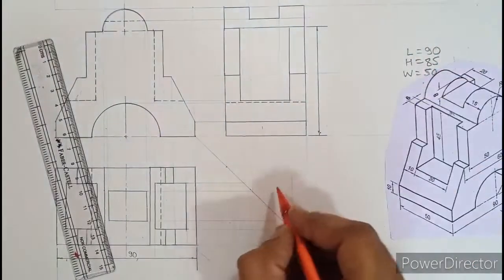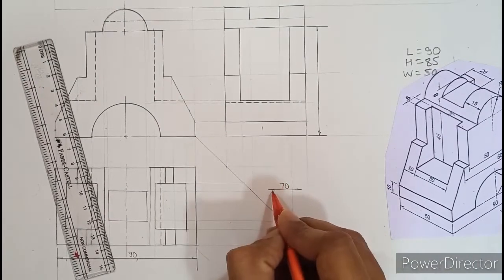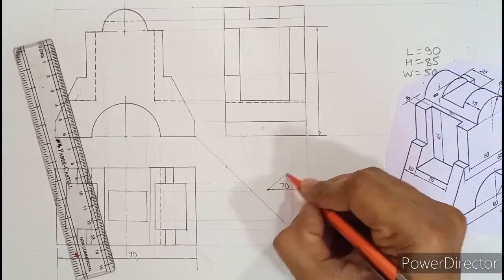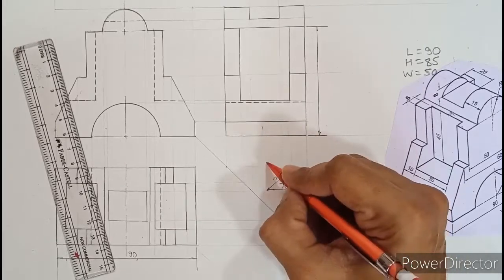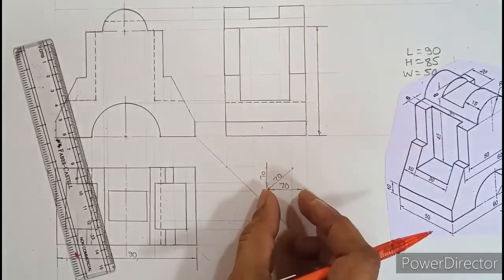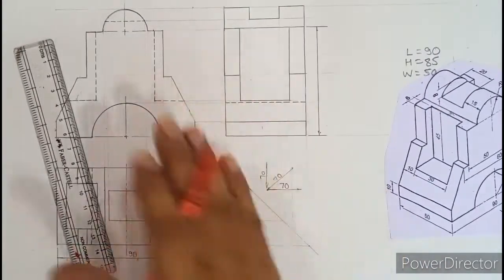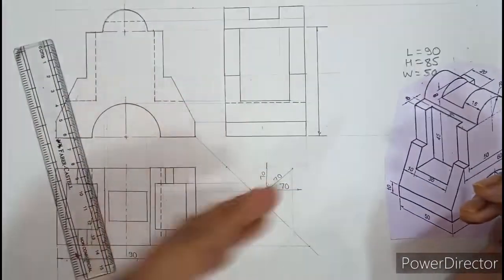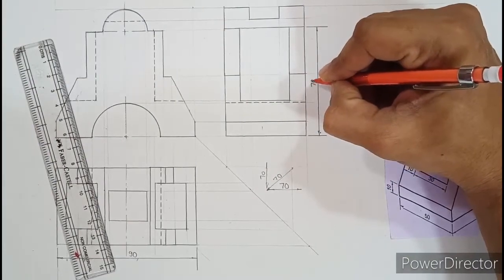All of you should know this: whenever you write a number, assume that the left side is your hinge and slowly swivel. When you swivel at an angle, 70 will still remain attached to the line, and when you make it vertical, 70 is written on this side. So the number along with the line slowly rises up, and that is how it is written above the line. Same way when you write 70 here, 70 should be written like this.